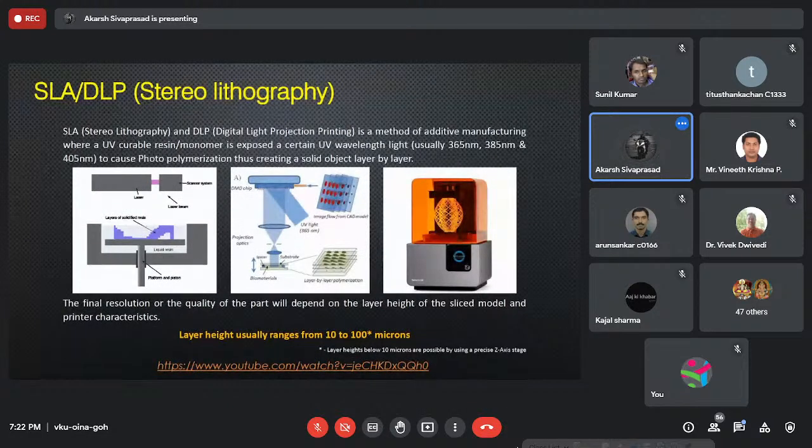And then yep, you keep doing that. What this resin is, is nothing but a monomer of uncross-linked substance. It can be anything like polyethylene glycol, acrylate, or something, and then you mix that with a photoinitiator and a cross-linker, and once you shine the light, it completely cross-links and becomes solid. So it turns from a liquid to a solid. That's how you solidify the layer. And then you keep doing that for all the Z, and then you get a 3D part.